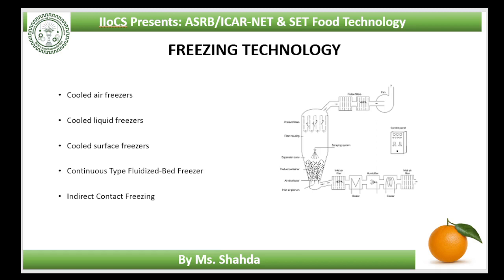Belt freezers or spiral freezers have a continuous flexible mesh belt which is formed into spiral tiers and carries food up through a refrigerated chamber, therefore self-stacking. This eliminates the need for support rails and improves the capacity by up to 50% for a given stack height. Cold air or sprays of liquid nitrogen are directed down through the belt stack in a counter-current flow, which reduces weight losses due to evaporation of moisture.